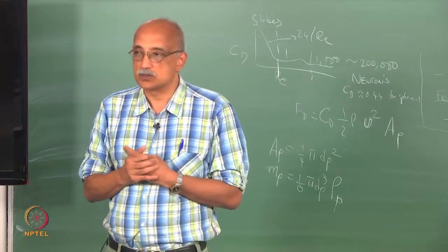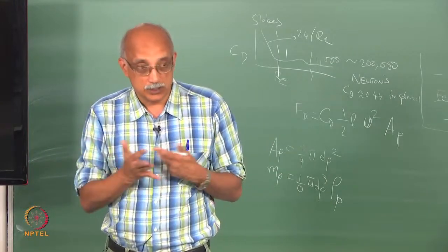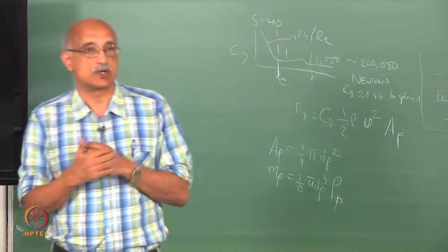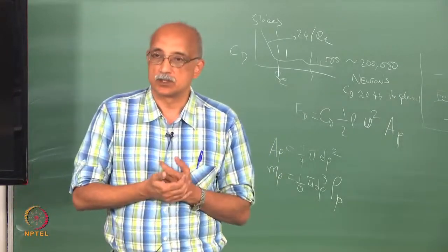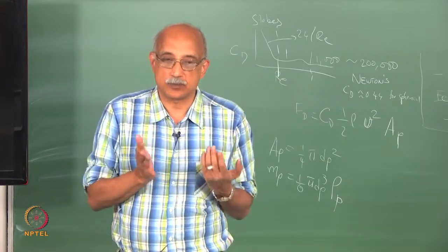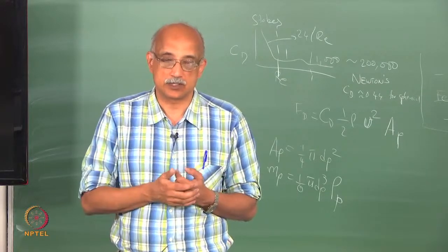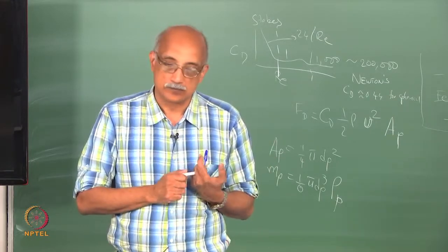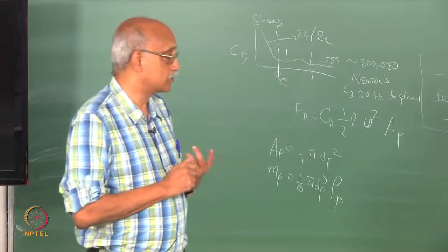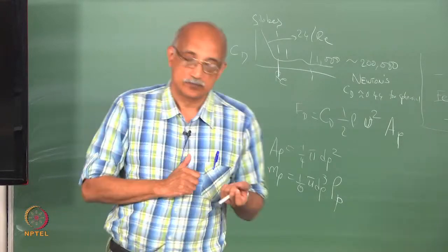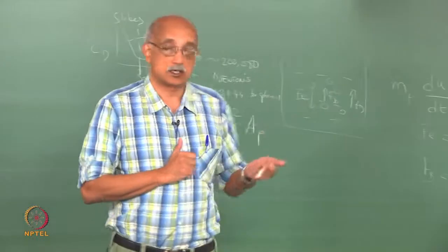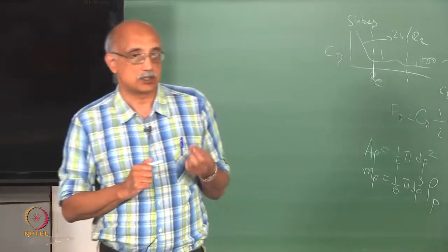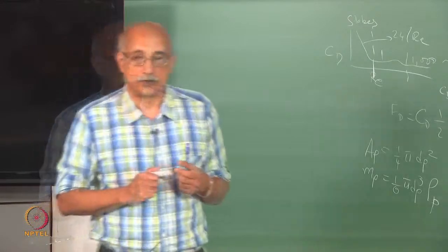The other reason, of course, is small particles have a greater mobility because of diffusional characteristics. So, it is more likely that two adjacent particles will eventually physically come in contact. Basically, the propensity or potential for sideways motion or three-dimensional motion is greater for finer particles. So, in fact, in the case of fine particles, the hindered settling velocities can be as little as 1/10 of the settling velocities in the absence of the hindering.